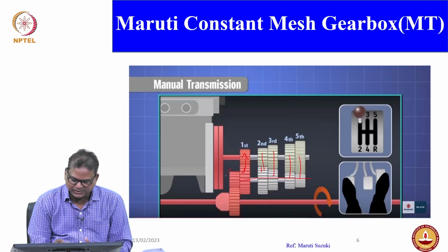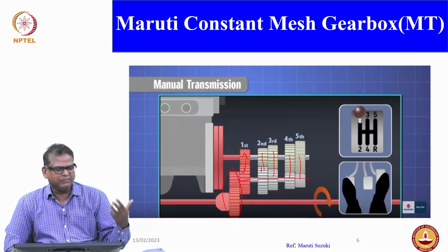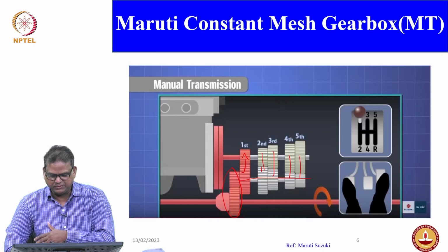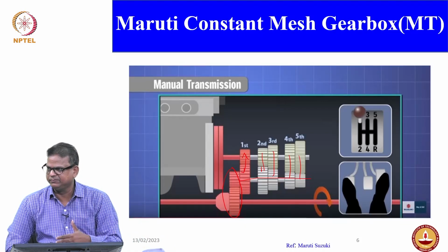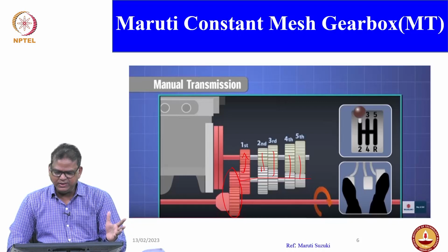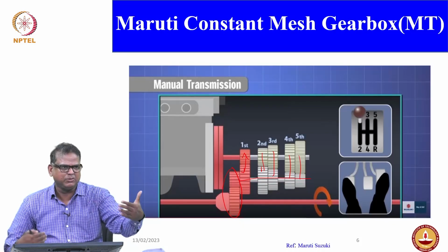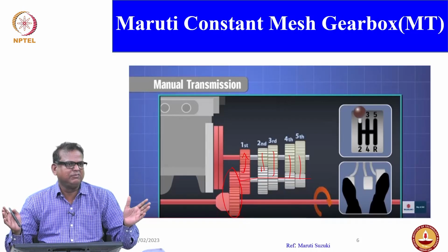They make the reduction either at the beginning, if the arrangement is possible, or else you can do it at the end also. Okay, which one is better? At the beginning or at the end? Beginning is better, because by doing that I don't need to have another shaft. It will make the size even bigger. If you do it at the beginning itself, my size will be even more compact.